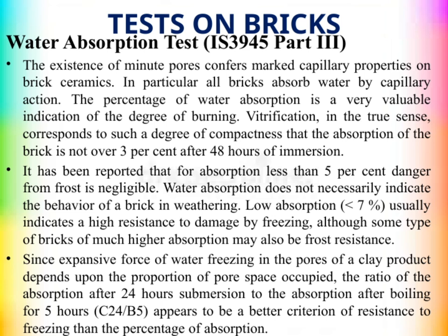Research shows that if a brick absorbs less than 5% water, the risk from frost damage is practically negligible. However, it's important to remember that water absorption alone doesn't tell the whole story about how a brick will behave in weathering conditions. In fact, bricks with low absorption, less than 7%, generally have high resistance to damage from freezing and thawing cycles. But interestingly, some bricks with much higher absorption rates can also be frost-resistant. The key factor here is the amount of pore space filled with water. The expansion caused by water freezing inside those pores depends on how much pore volume is occupied.